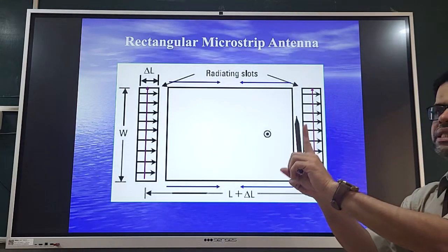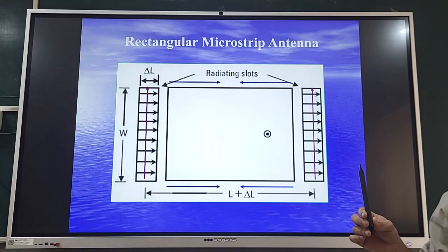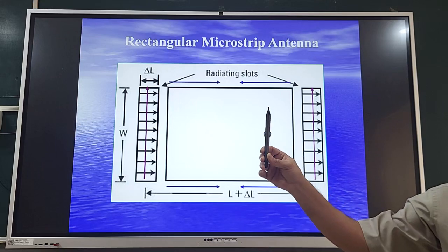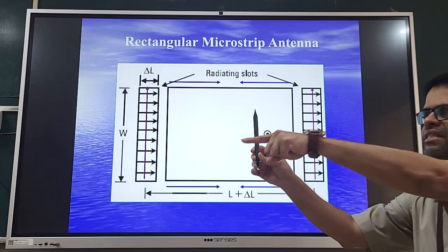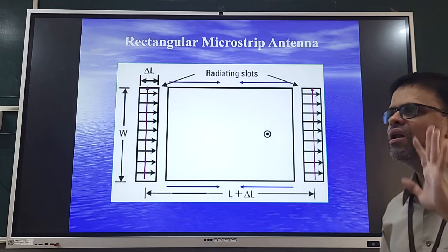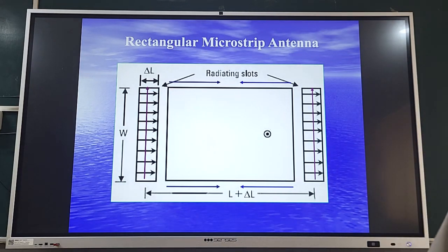Now when the two polarizations are matched, then naturally you will get maximum power. Suppose now this is the antenna polarization of the receiver antenna and the incident wave is orthogonal or perpendicular. What will happen? Dot product is 0. That means your antenna cannot receive any signal from the orthogonally incident wave. Thus, the cross polar level of your antenna defines the susceptibility of the antenna to receive orthogonal waves.